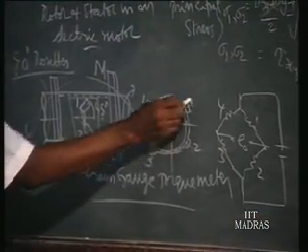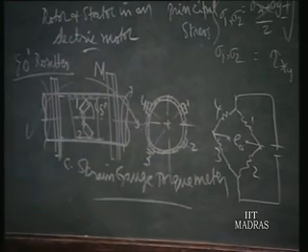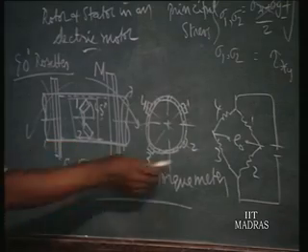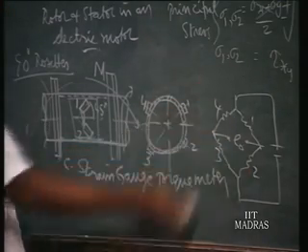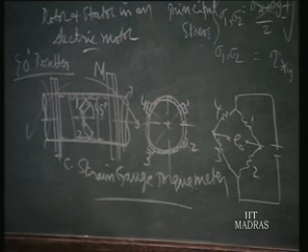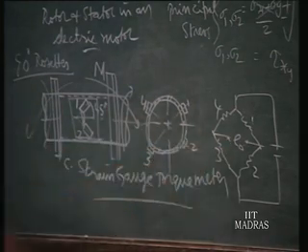So 1 and 4 are the strain gauges which will be subject to tension. Now 1 and 4 are in adjacent arms taking up similar strain, and it will nullify, so it will not give rise to any output voltage. Similarly, 2 and 3 will be under compressive strain, in adjacent arms, and will not give rise to any output voltage. Hence the bending moment does not produce any signal in the bridge network.